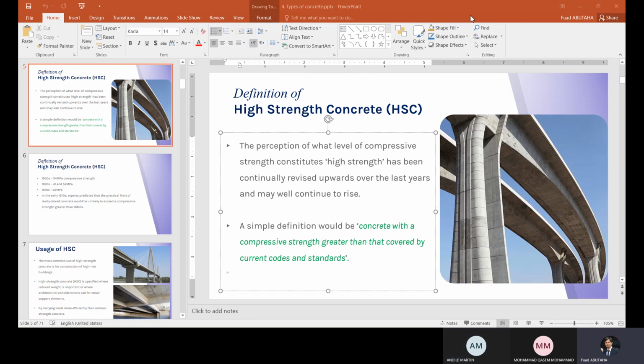Always, the use of a small particle will increase the strength, right? But it will decrease the workability. The small particle will make the concrete quite stiff, harsh, and difficult to handle. But if we use large particles, it will improve the workability of concrete.